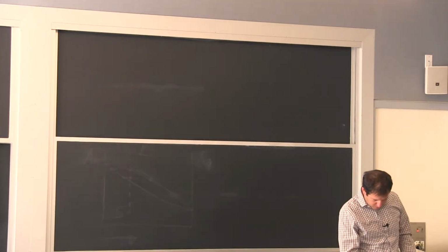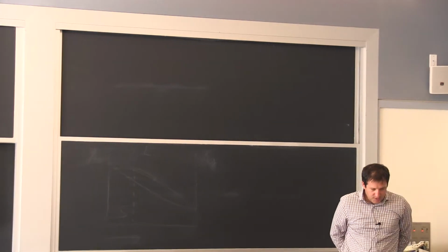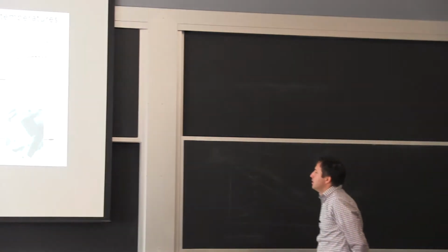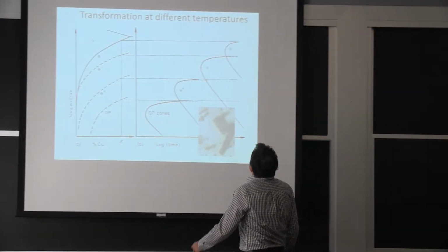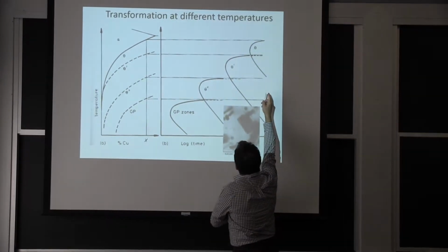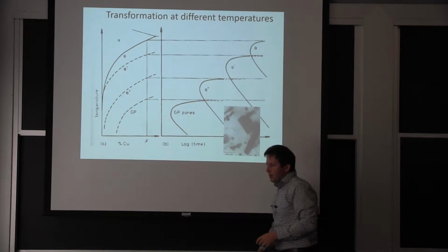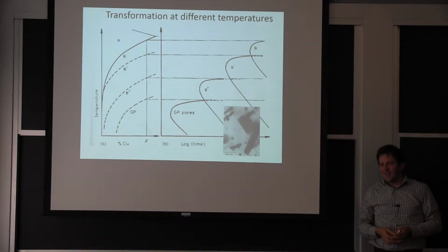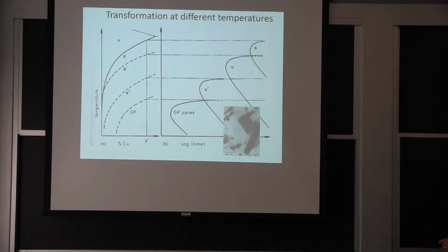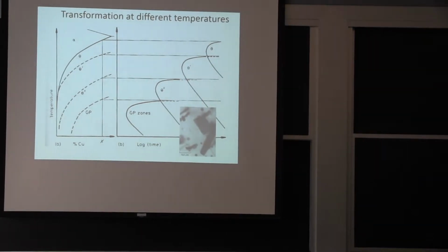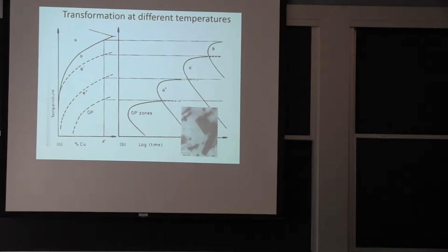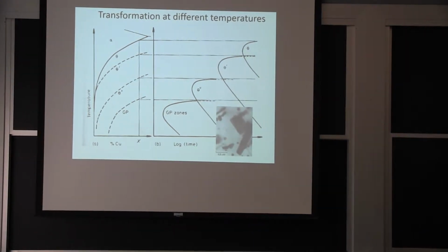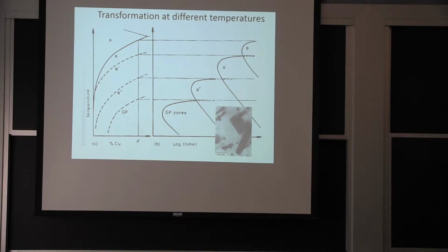And we have a zoom out here with the different types of non-equilibrium phases. So you can see this is the equilibrium phase, the top one. All the others are phases that become equilibrium given the kinetics. They're metastable phases, essentially. So they will form because when you have the noise in the microstructure, eventually they combine and they'll be all together. Instead of disappearing, they grow from there and get towards equilibrium gradually.